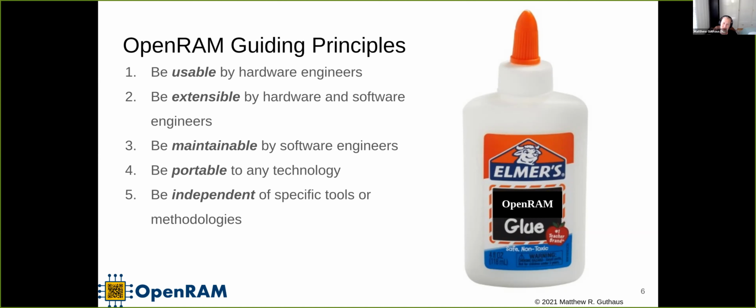So kind of the idea of restrictive design rules, where you may say, just do the easiest thing rather than the thing that gets you the most density if area doesn't matter in something. The example I like to point out is in the control logic, you use a couple NAND gates. We don't need the area of those NAND gates to be highly optimized because you use like 3 of them, and that doesn't really affect your overall area of your memory. But if it's in the decoder logic, for example, then it's replicated across the entire side of a memory and it does matter. So we try to focus on things that really have an effect.